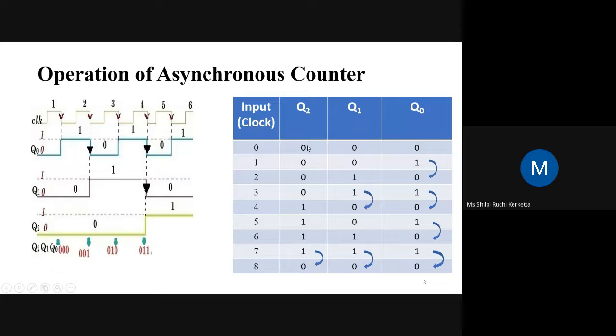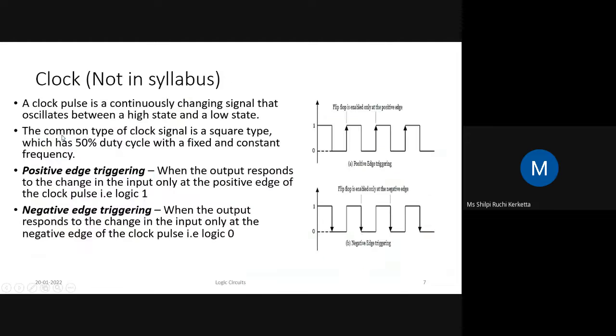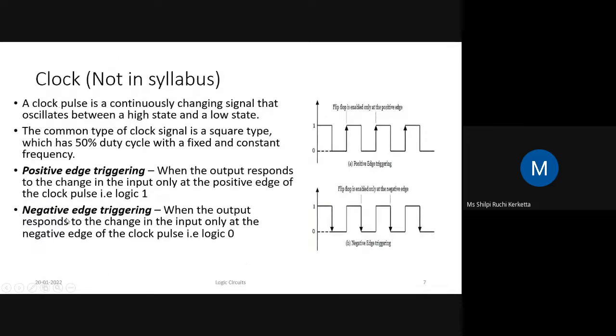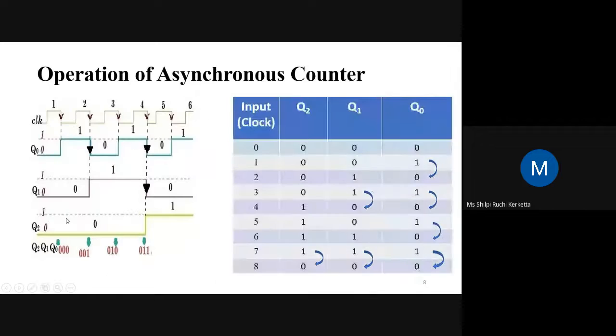Okay. So here we can see that 4 zeros are there and then 4 ones are coming. So here if we give a clock, first we will see that we have given a 0. Okay, so it is JK flip flop. So this first flip flop, it will work. As we are giving this first clock pulse and it is negative edge triggered, so we are giving a 0. So here it is negative edge triggered.